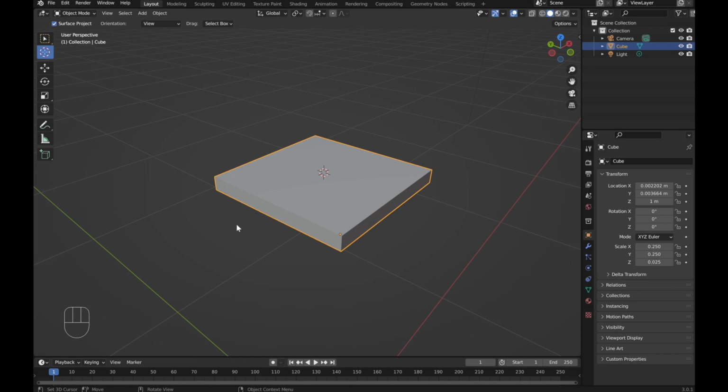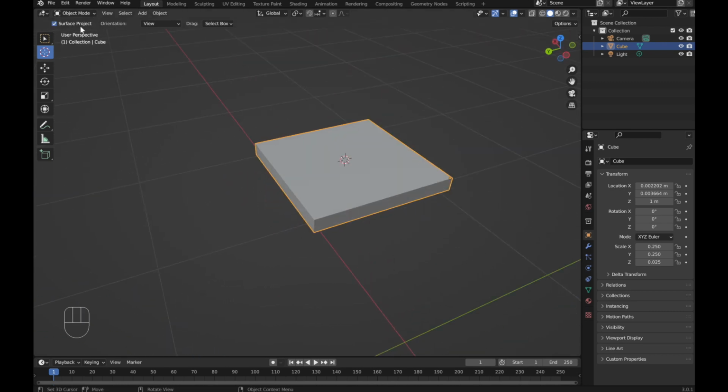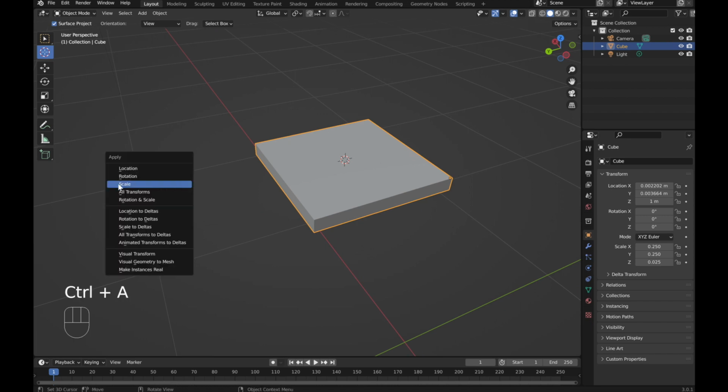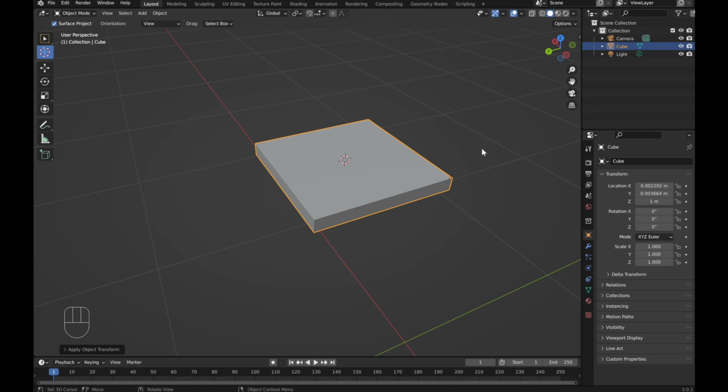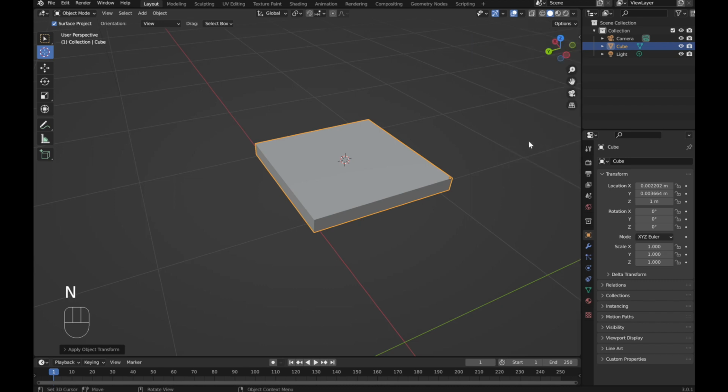Next, I would like to round the corners of the seat. First, confirm that you are in object mode, select the cube, and apply scale from Ctrl+A. If you press the N key and check the scale in the Item column on the right side menu, you can see that it is 1 by this operation. With this, the next corner will be cut at 45 degrees, so perform this work once.